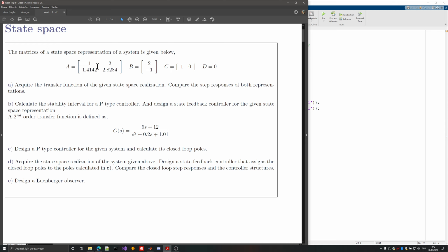So now this observer basically copies the system and is kind of like the model matching controller, or the Smith predictor. It includes the system model again in it, so it is an nth order system. So you need n integrators, but you're creating the same model and you're feeding back the error between the output of the actual system and your predicted output.